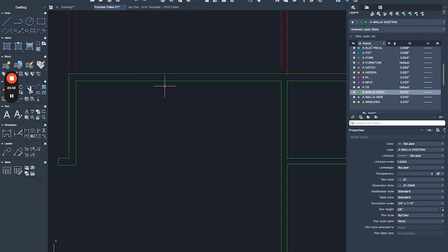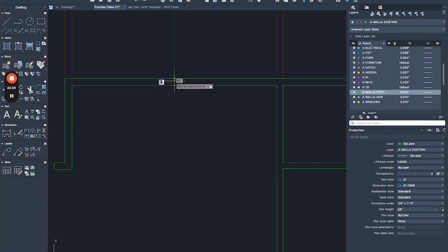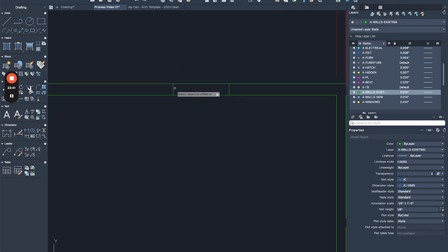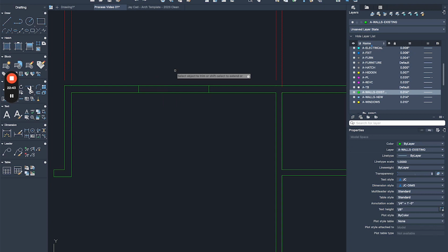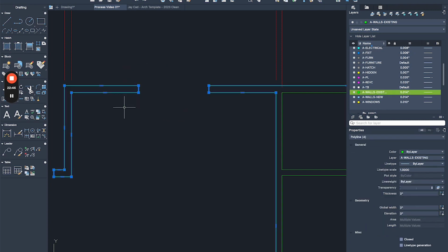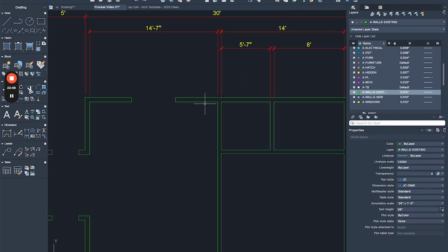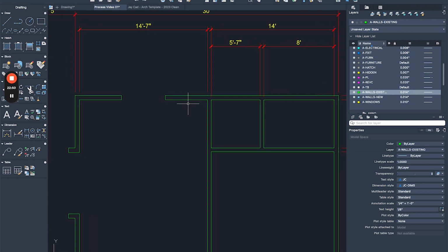Here I want to put my kitchen window right smack in the middle. I'm going to put a window right above the sink, so I will do that. Then I want to do a window that's 5 feet wide, so I'll do it like this. Then I will erase this, trim it, and then join. I know the join part might not make super sense yet, but you'll see eventually.